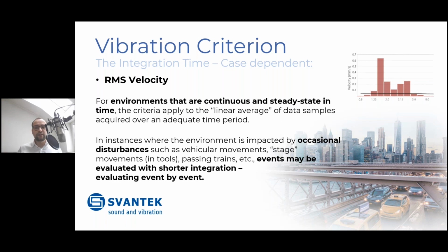Martin has a great example in his real VC presentation on the actual applications. I think it's very important to know that if you are measuring somewhere with a fairly steady state condition, where the vibration level is not changing over time too much, then a long integration period can be sufficient because there are no transient occurrences.